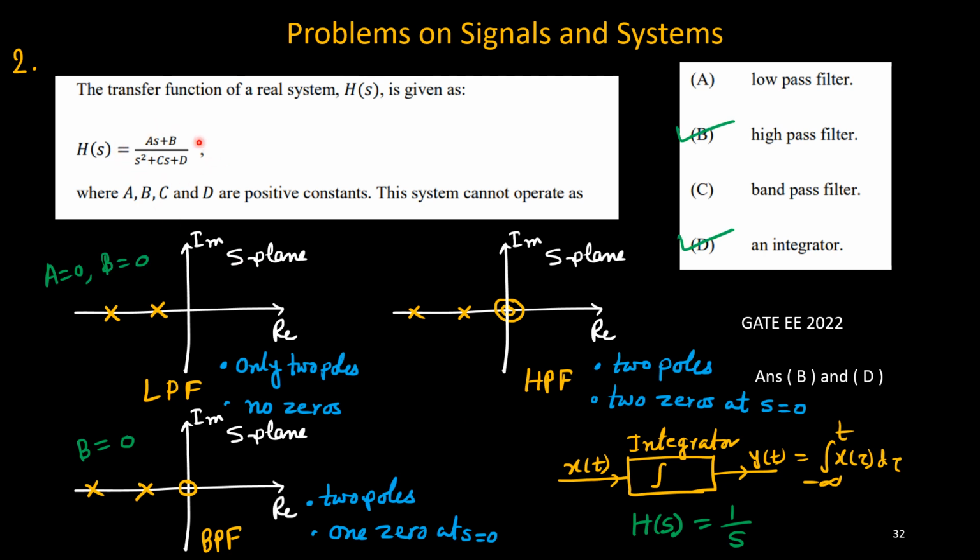So from that, easily we can make a low pass filter, because this is not actually b equal to 0. This b should be equal to 1 and a equal to 0. Okay, so this b equals 1, remember this one correction. So b equals 1 and a equal to 0 will give you a constant numerator 1 and denominator 2 poles, right? So b should be equal to 1 here and a equal to 0, or b can be constant also. Okay, not necessarily 1, it could be constant as well.